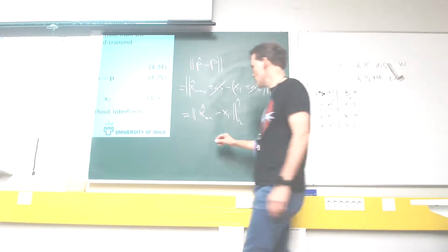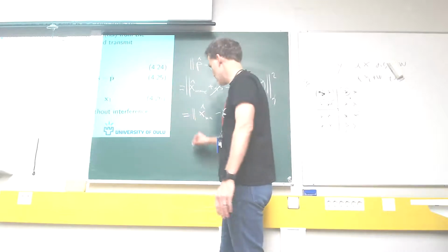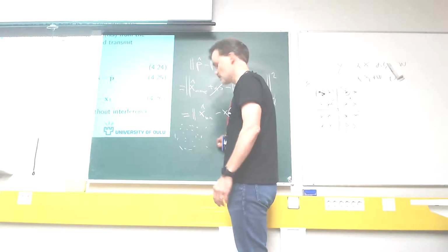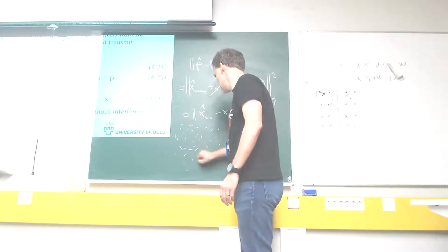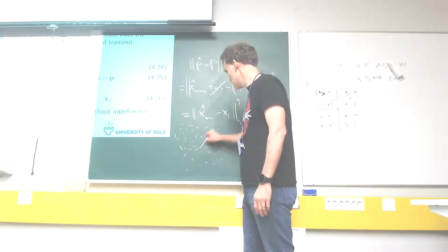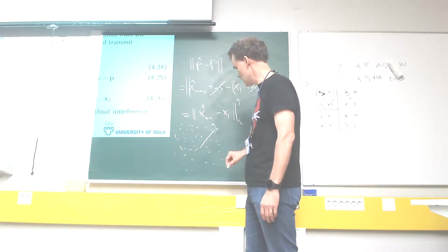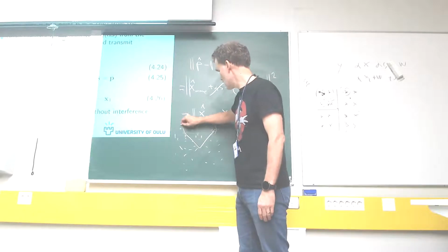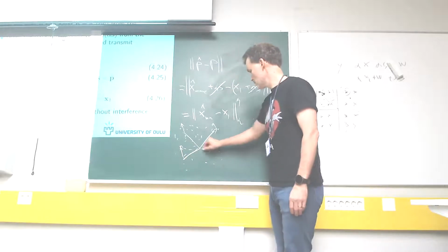Of course, this is a very simplified scenario with, let's say, QPSK, but then like a Gaussian alphabet, this is projected to 2D now. You are just replicating all these points, and if alpha is here and this is your desired point, you're sending this vector. If alpha is here, this is your desired point, you send this vector, and so forth, right?